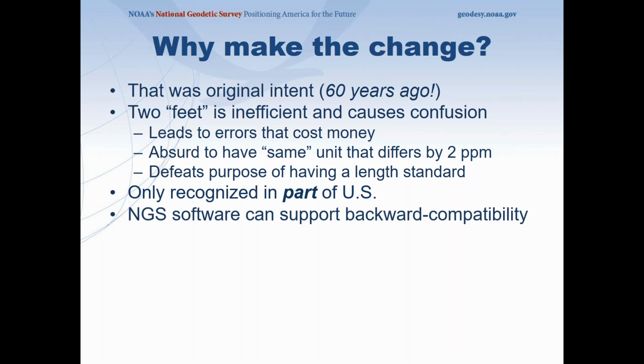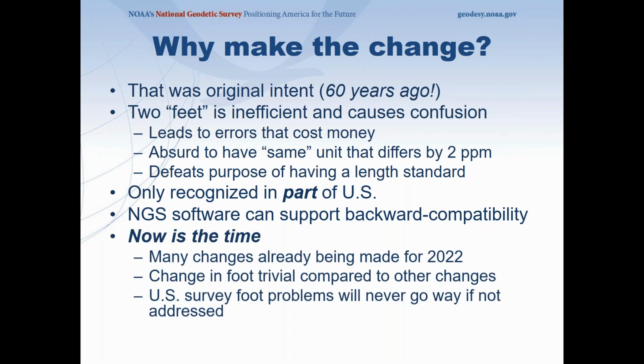NGS is going to have software that can support backward and forward compatibility. And now's the time to change, because we're getting ready to do all these other changes with the 2022 datum. We said changing the foot is a trivial change to be made. And now what we mean is we're going to change to using the international foot, or the foot as some people are going to call it, when you get a product from NGS.